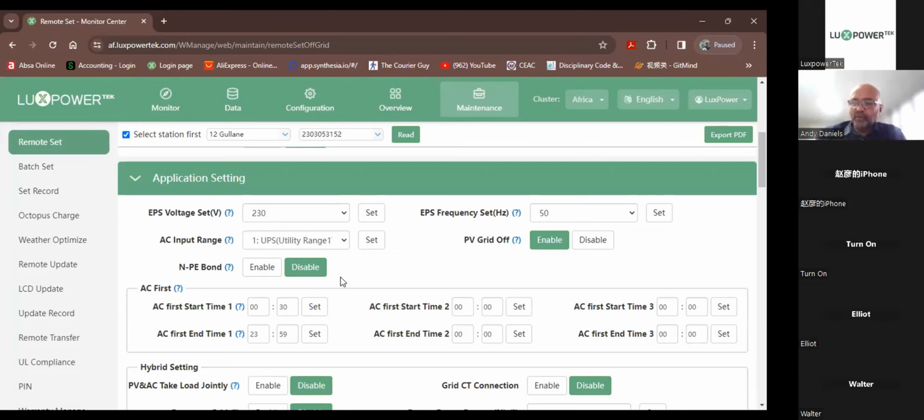If you put your machine into off-grid mode and you measure the AC voltage between the neutral and the potential earth, you should get 0. If you have an elevated voltage of 95 or 115 volts, it simply means that your bonding is incomplete.